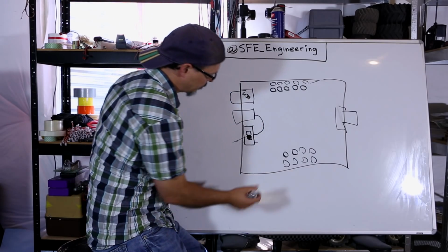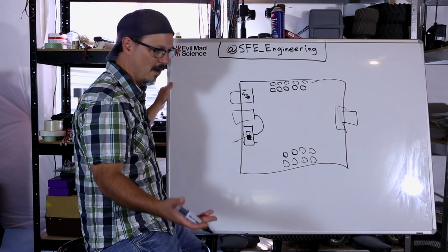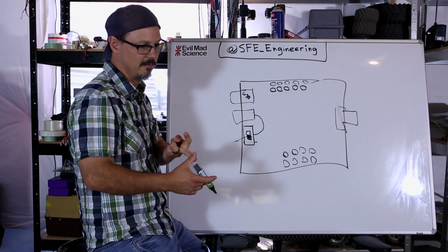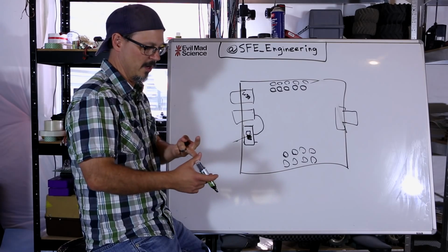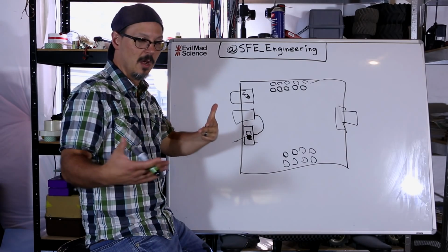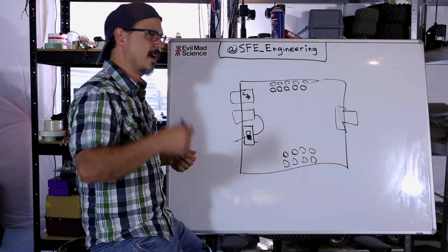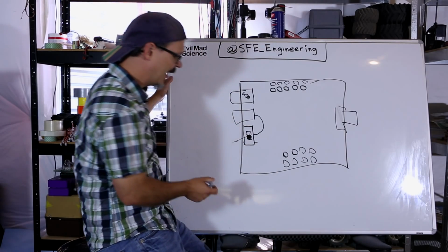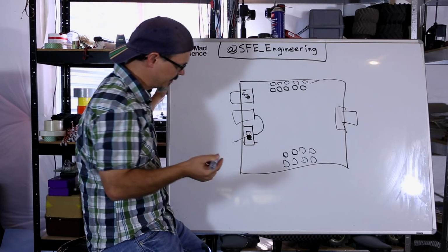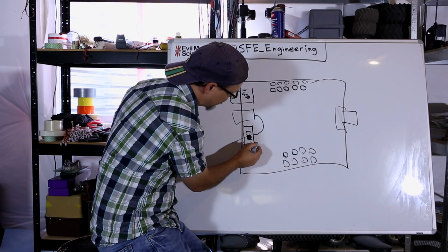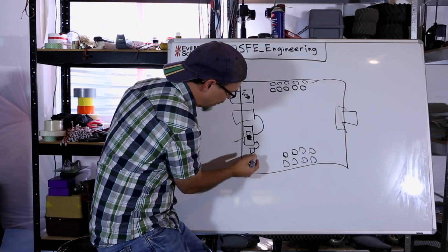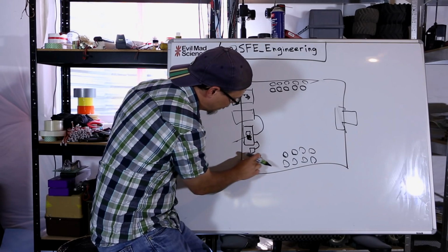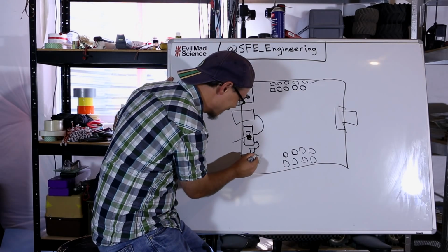So now what? Well, generally, just like the schematic's going to show, it's going to have a cap on the input, then probably a TO-220 or a SOT-23-5 package regulator, like a small current regulator, and then a cap on the output, maybe another cap on the output, ceramic and tantalum. And so what I will normally do is I will pack that circuit section off, right? So I'm probably going to run this too, and there'll be one cap, and then the regulator might be here, or actually, right, this is an iterative process, and I'm iterating right now.